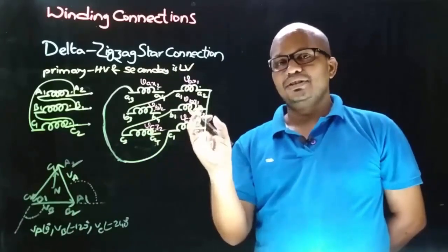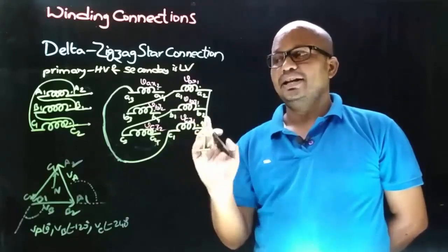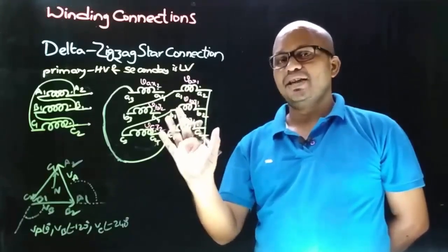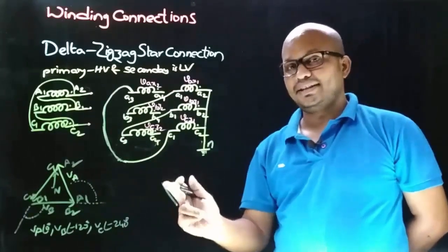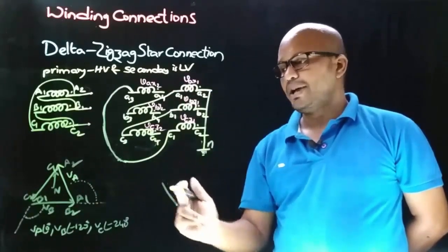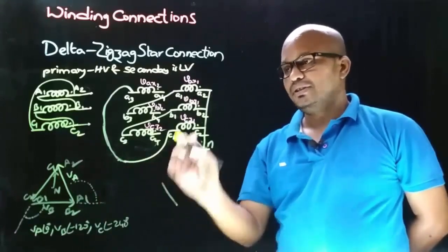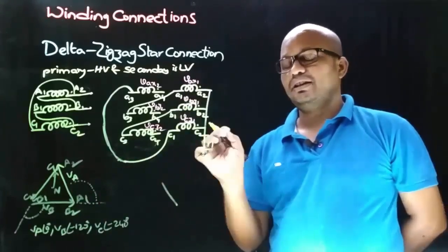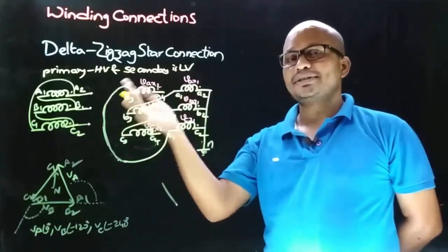So first let's draw the phasor diagram for this star connection, and it is known that the secondary side phasors are drawn parallel to primary side phasors. So let's draw the secondary side VA X1 phasor parallel to primary side VA phasor, and now we need to decide the direction of the secondary side VA X1 phasor, and the direction of phasors depends on the connections we took on primary side and secondary side.